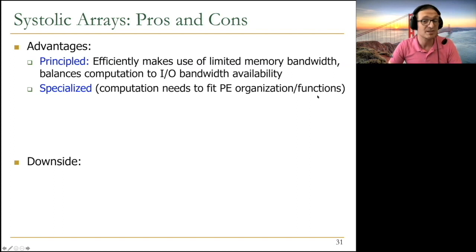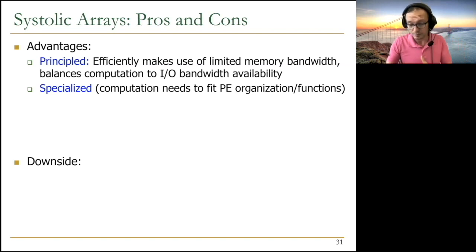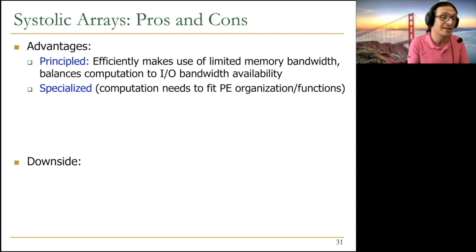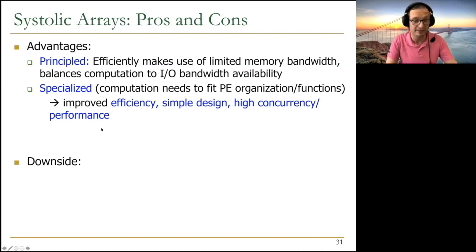And it's also specialized because it has a particular computation in mind that it can do very, very efficiently. It's implemented to do that computation. But the computation needs to fit the processing element organization and functions and the array organization as well. And if that is the case, then you get highly improved efficiencies, simple design, high concurrency, and high performance all at the same time. It's a very nice accelerator for that purpose.